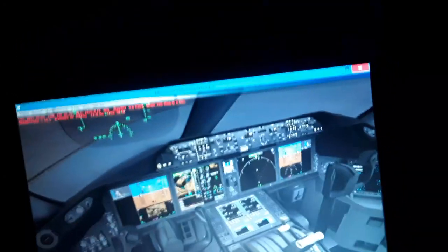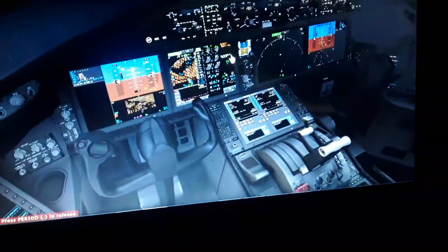So I'm gonna use the flight management computer to input all the data of the aircraft. As I told you, we're gonna select the departure runway. We're gonna use the flaps for takeoff, the gross weight of the takeoff, the mean aerodynamic chord position through the center of gravity, and the horizontal. This is gonna give us, using the flight management computer, the horizontal tail trim stabilizer position for takeoff. Then for climb, cruise, approach, descent, and landing. So we're gonna have during the whole flight the horizontal trim stabilizer, either automatically set or manually, using the trim tab over here. You can see we can trim up and down.